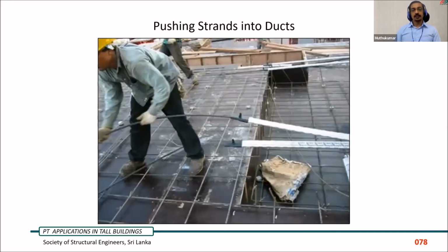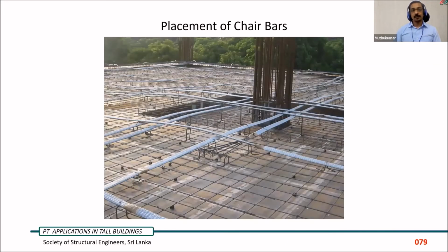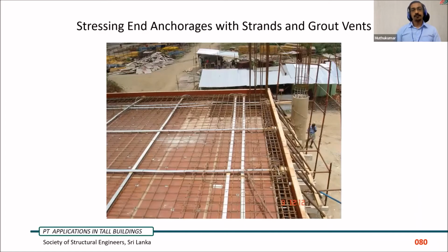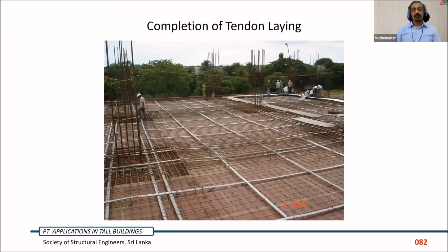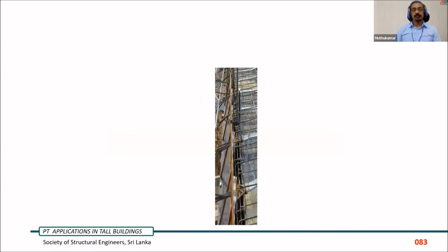Cutting off strands, then pushing the strands inside the ducts. Placement of chair bars to create the profiles to get our expected uniform upward loads. The stressing end has to be fixed with bursting and spalling links to withstand the force. The dead end is prepared with grout vents for grouting. Upon completion of tendon laying,